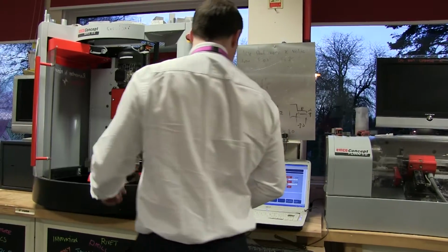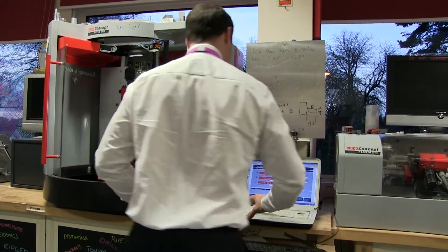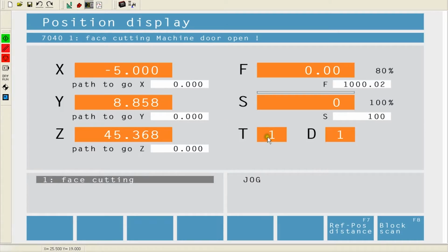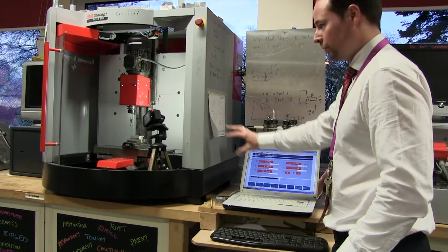the machine. So I'm using tool 1, that's the first thing to check. If you need to change this, if this was set to tool 2 before, I just change this to tool 2, and I click in this and go back to tool 1, you'll notice that it says change the tool here. In order to get rid of this, I have to actually click reset over there. So it's this middle red button. So just be aware of that, otherwise none of this will move.